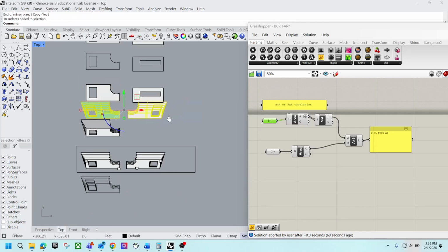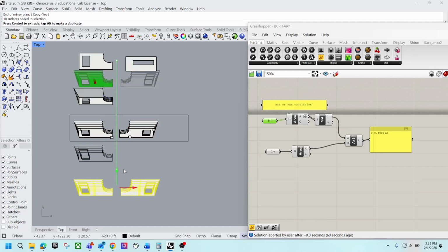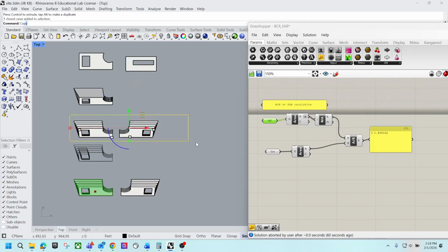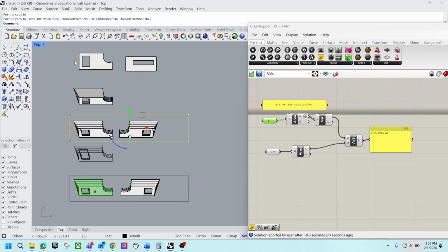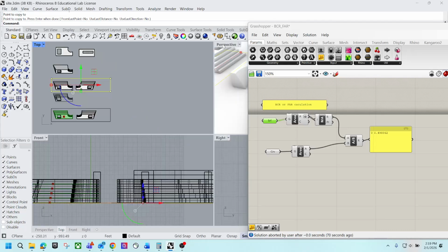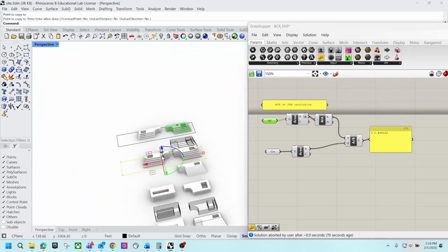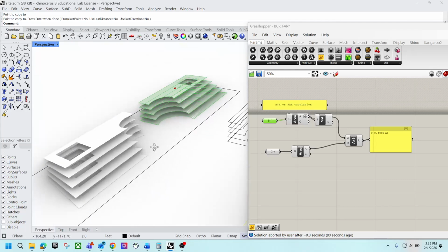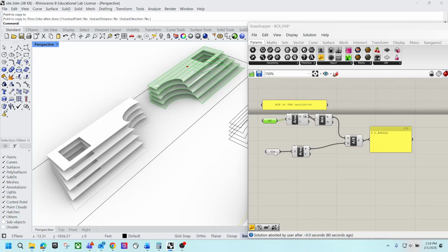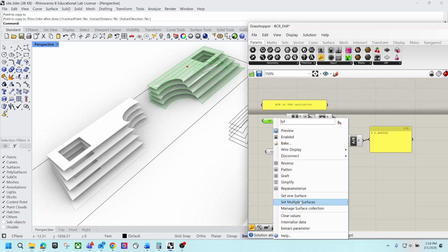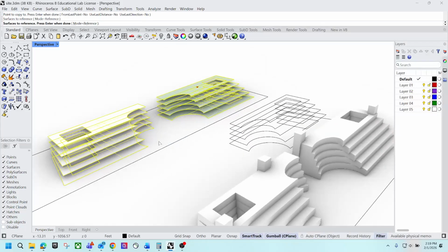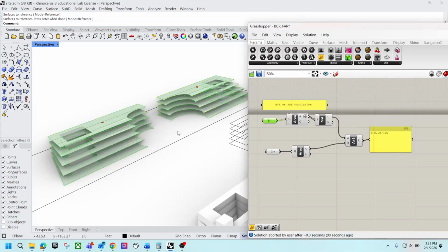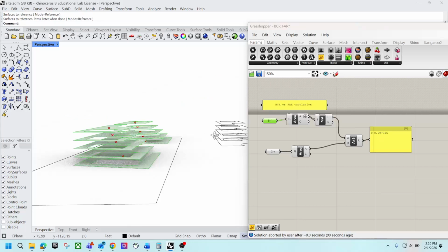I just make it a little bit lower so you can see it, and I will copy this to be consistent. All right. So now I have this new set of floors, just the floor slabs, and then I can reset multiple surface. Just make sure you pick all the surfaces, have 10. Now you have this FAR value at 0.99. That should be accurate.